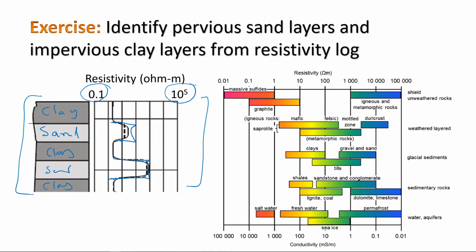And you see here, let's look even at this one. Yeah, see the sand and gravel, they have this range of resistivity here, and then the clay has this range of resistivity here, and it can go up to 100 ohm-meter. Remember I was telling you, you need to put this cutoff. See, the clay could go up to 100 ohm-meter, and you need to put this cutoff.